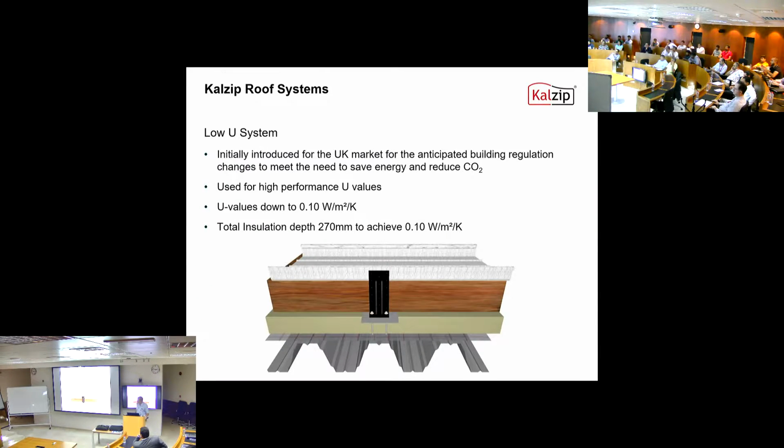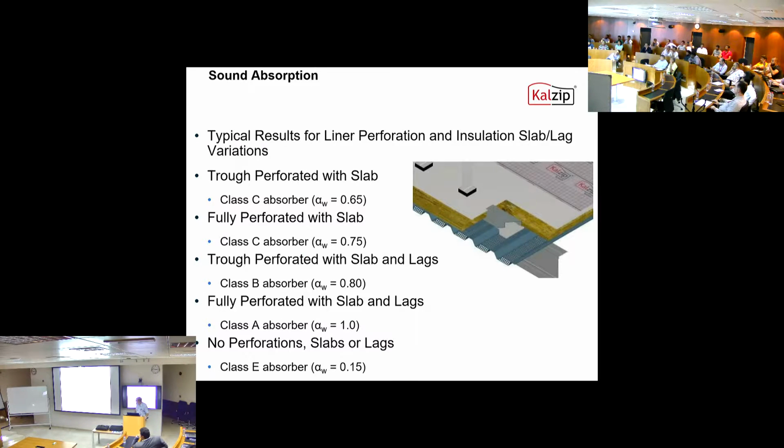How will the acoustic slab be fixed on the profile, and how will the hat be fixed on this? Yeah, this is a top hat section, an omega section. Yeah, so normally the acoustic slab would be 30 millimetres deep, so the omega section would be 30 millimetres deep, and the clips fixed. Okay. And the vapour control layer sits on top of the acoustic slab.